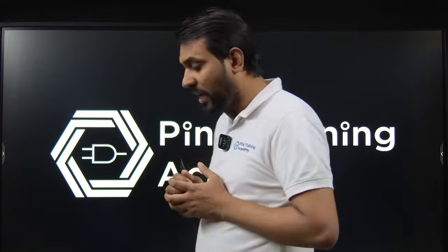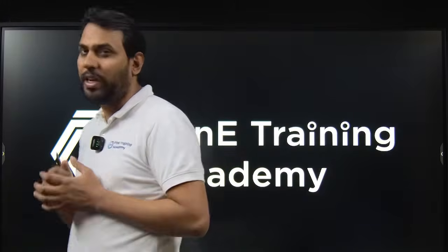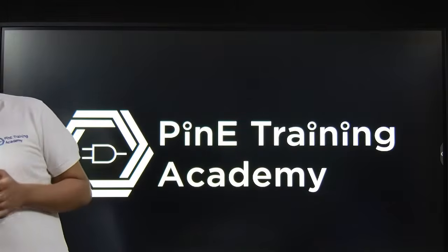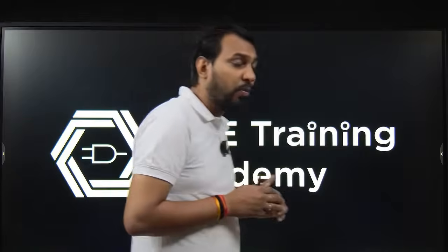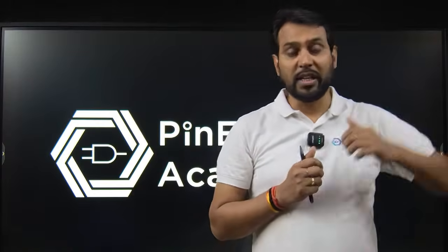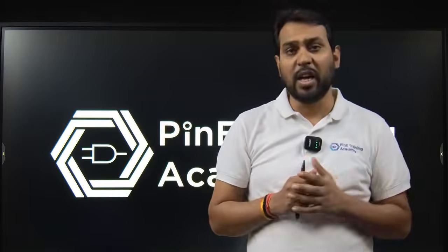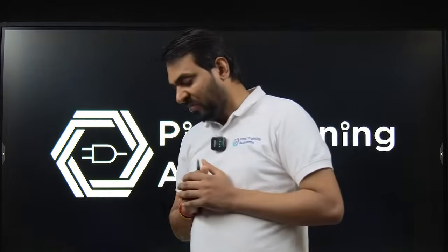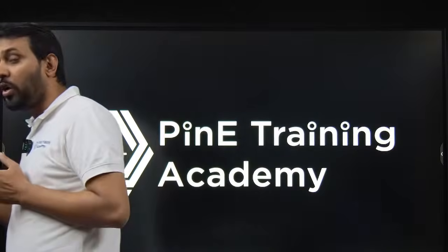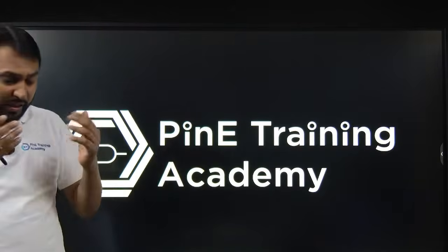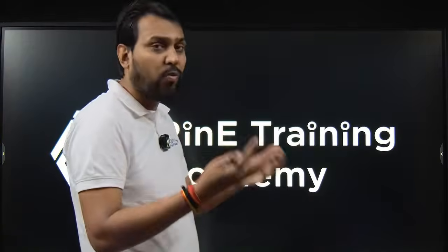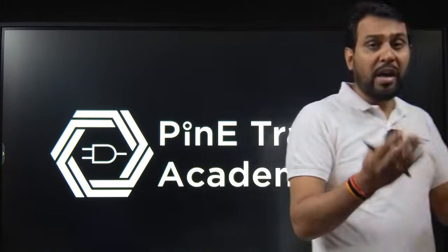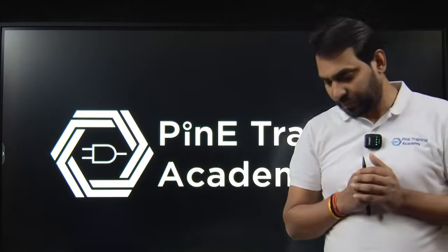And then we discussed the ideal voltage source, practical voltage source, independent source, dependent source. The dependent source is very important because this is the heart of the analog circuit. If you know the dependent source, you can analyze what is happening in the amplifier, in current sensing, in the ADC, in the DAC, because this helps to convert every non-linear model to a linear model. We have four types of dependent sources: voltage controlled voltage source, voltage controlled current source, current controlled current source, and current controlled voltage source. Every dependent source has its own capability.